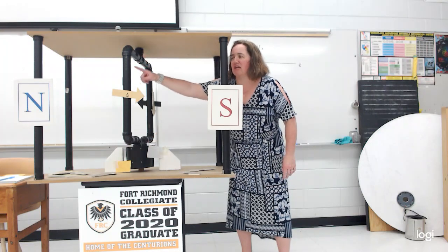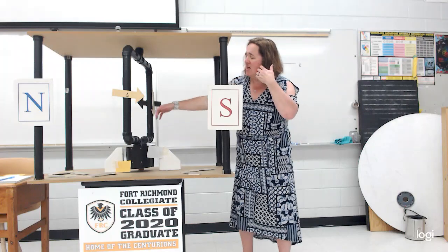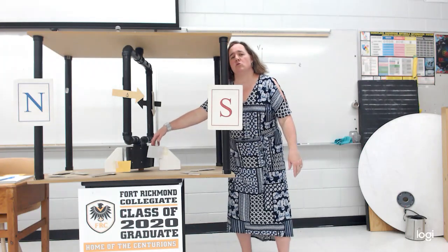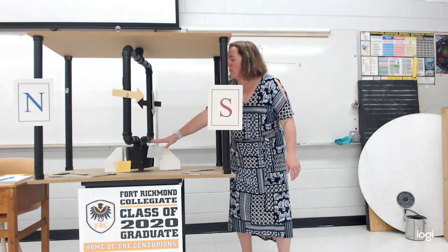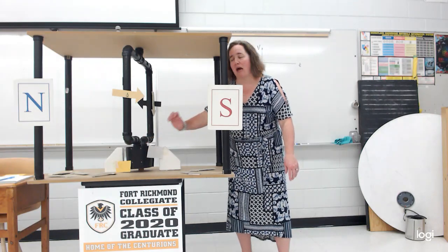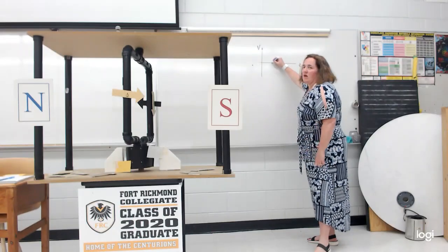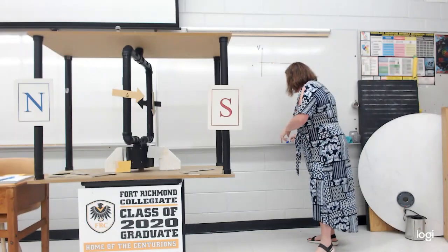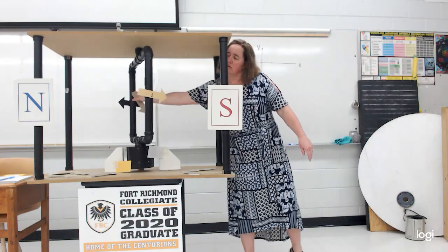So we're generating zero EMF and therefore zero current at the same time as those commutators are bridging the gap, right? So we have them going across the brushes, touching the gap right now. So we're down at a voltage of zero.